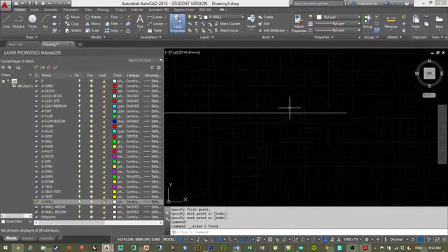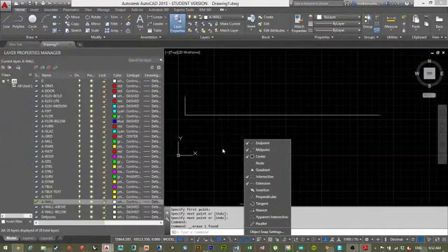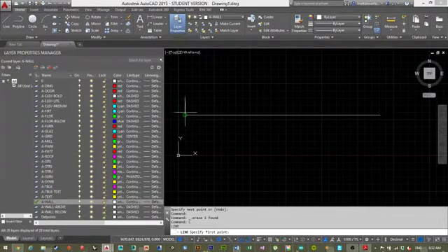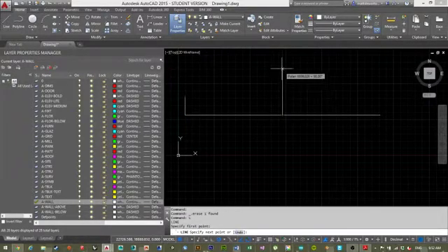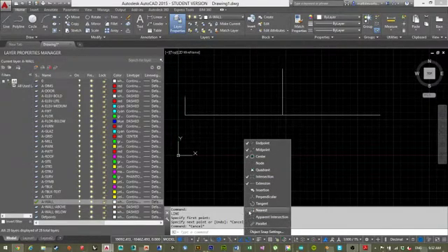So if I wanted to draw something right in the middle of this line, I can easily just go midpoint, turn that on. Now when I start to draw a line, you'll see it's at the ends, but it's also in the middle. No matter what, every line now has a middle snap point on it, and that's directly right in the middle. Turning it all on might seem like a good idea at first, but if you start getting a busy drawing, it'll just be snapping everywhere, and you won't know which one is the right one. Yeah, that looks about right.